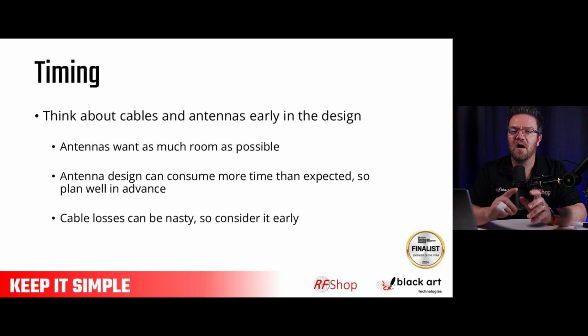You need to know what the effect is going to be of making a tight space with a very small piece of electronics, and say, okay, and then the antenna just needs to go there. So there's going to be a price to be paid if you don't give the antenna the respect, let's put it that way, it deserves. Also, cable losses can be nasty, so don't forget that the cable decision is important, and the bigger cables might be what you need. The more expensive cables are maybe what you need.